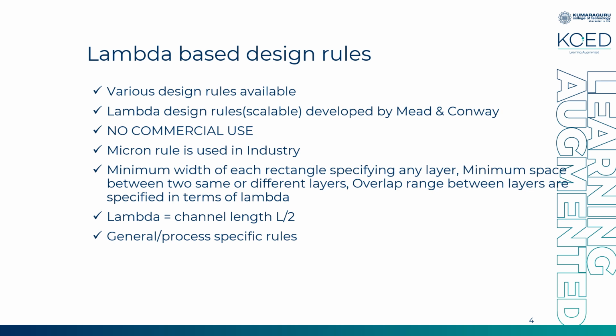Feature size is your channel length. Suppose I am designing a system with 180 nanometer technology. What is my lambda? 180 nanometer by 2. Suppose I am designing with 90 nanometer technology, my lambda will be 45 nanometer.